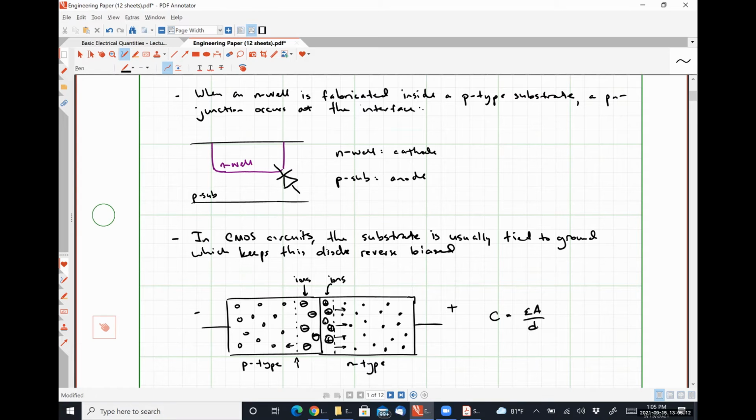So even though we're uncovering more and more charge, the cross-sectional area of the plate effectively doesn't change at all, right? Because it is just that surface that's moving back and forth along the X direction here. But the distance between the plates can get appreciably larger depending on how far we reverse bias this guy, right?